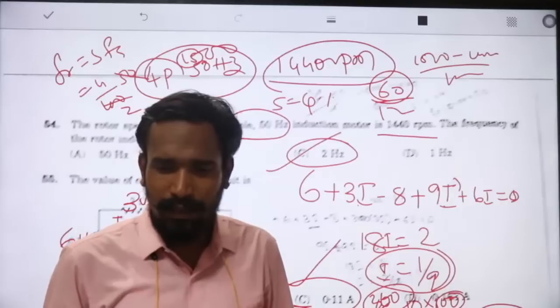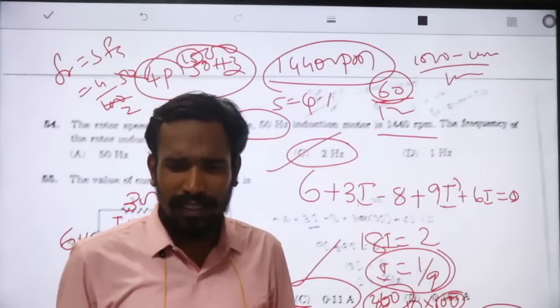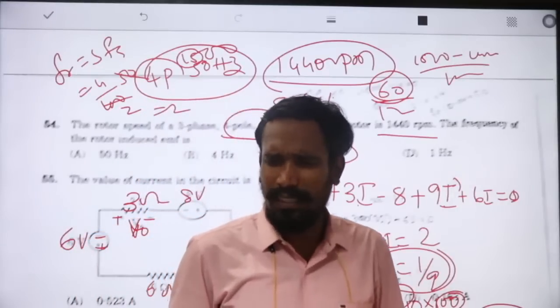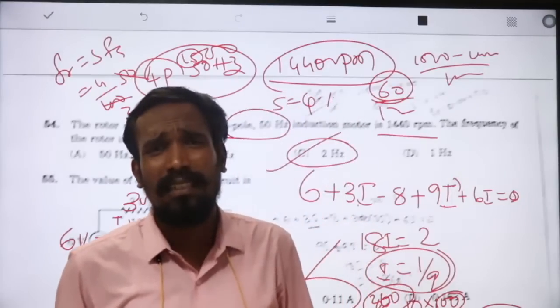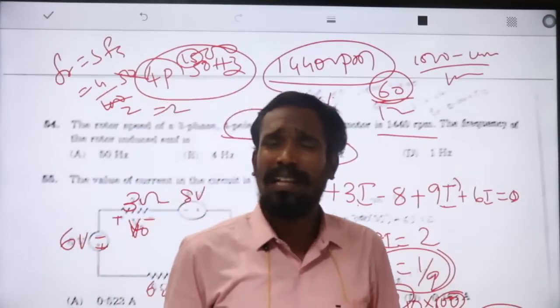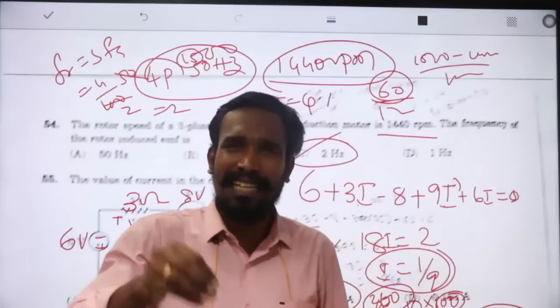Okay. It depends on rotor frequency, no hysteresis and no eddy current losses. Yes, sir, no hysteresis and no eddy current losses, because the rotor frequency is very much less, that's why no core losses. We neglected them; they are there, but we neglected them.